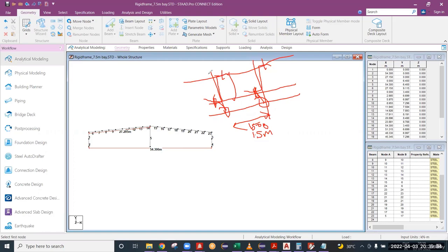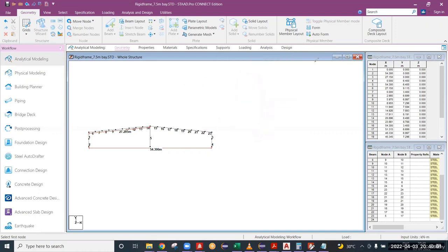Generally, if you observe the purlin weight, it will be 3 to 7 kg per meter square over the rafters. If you calculate after the design, the purlin weight will come under 3 to 5 kg per meter square over the plan area. That is how practically they will come. So it is clear now? Clear, sir. Okay, thank you.